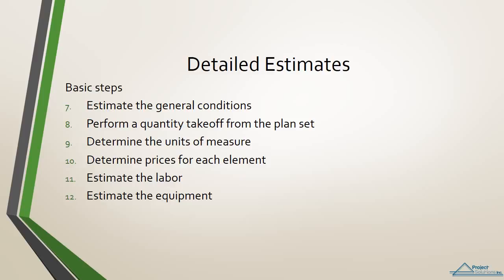Number 8, perform a quantity takeoff from the plan set. Number 9, determine the units of measure. Number 10, determine the prices for each element. Number 11, estimate the labor. Number 12, estimate the equipment.